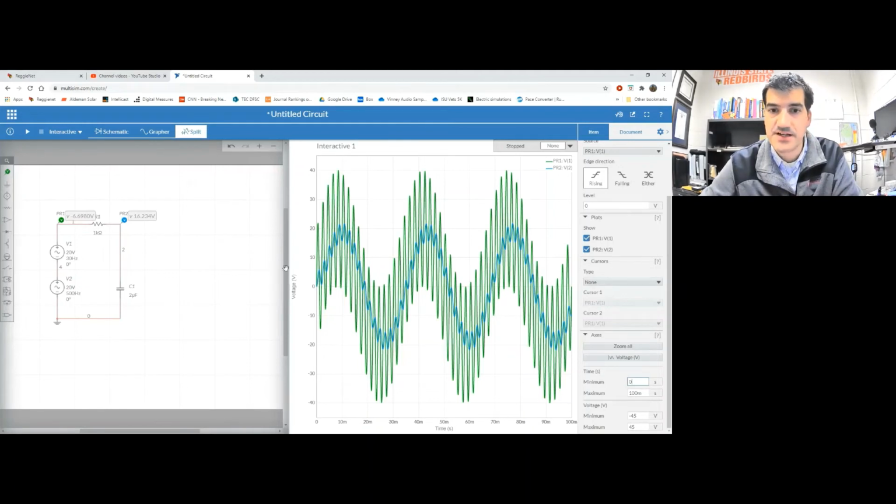It's worth noting that just because your frequency is above the cutoff frequency doesn't mean it's going to block it. You see what I meant before where I said it attenuates it, not blocks it? Even though 500 hertz is well above the cutoff frequency, we have not completely eliminated that high frequency from our output. We've only attenuated or minimized it. It's still there, just much lower in magnitude. Let's keep going. I'm going to double it again.